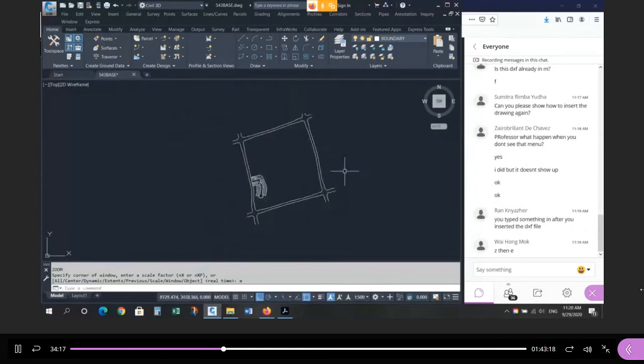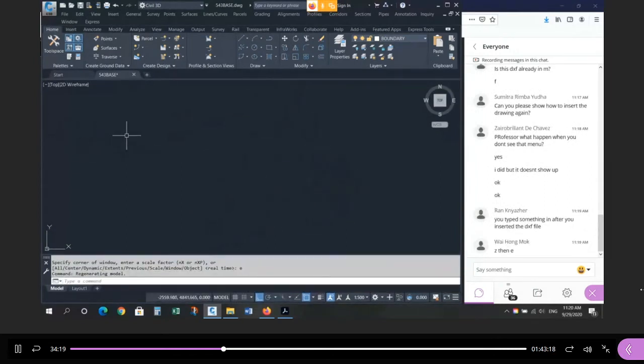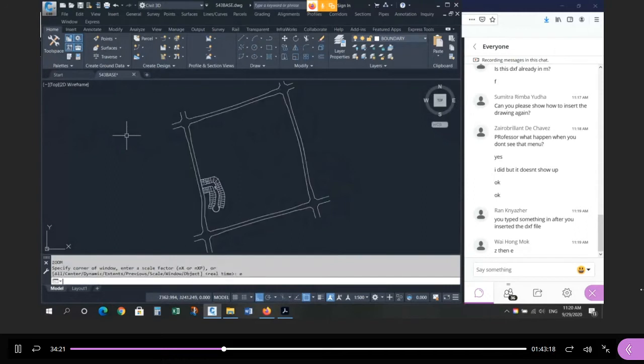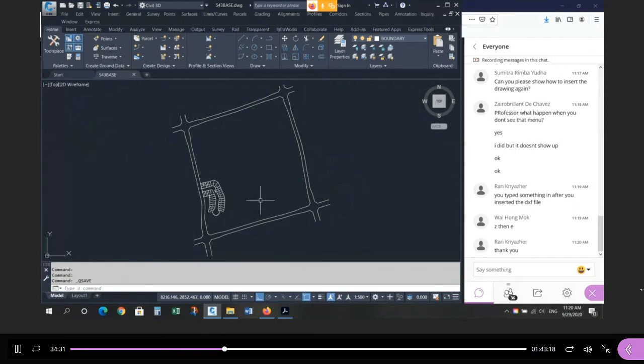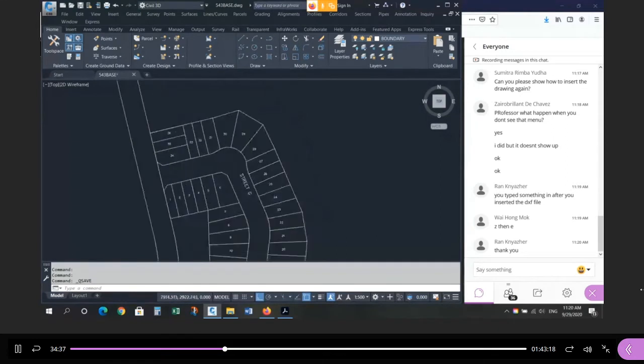Yeah. Because what happens is, you're zoomed in here. It's in the drawing in the right spot, but if you don't zoom extents, you won't see it, right? You're zoomed in somewhere over here where there's nothing to see. Okay, so after you insert it, zoom extents. Okay, so now if everybody has their site, again, delete the ones that weren't assigned to you, zoom in and